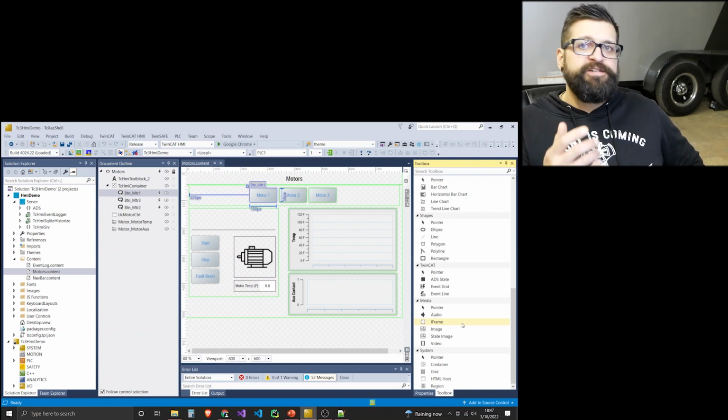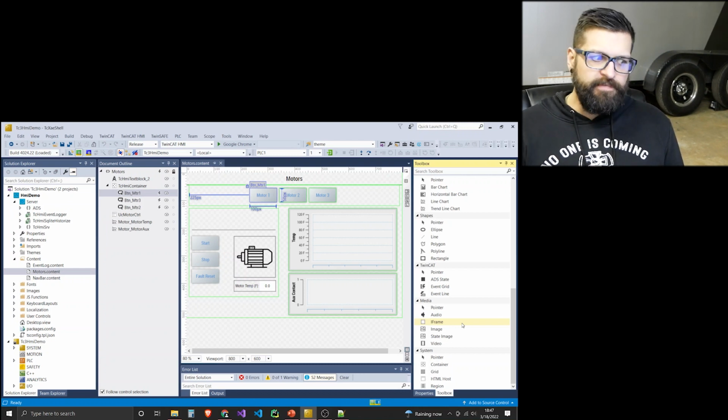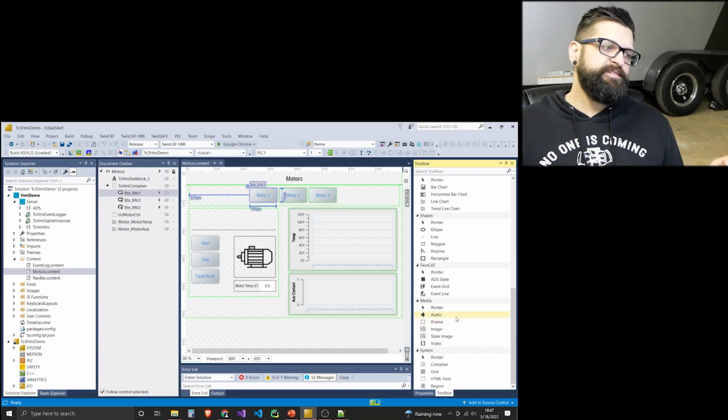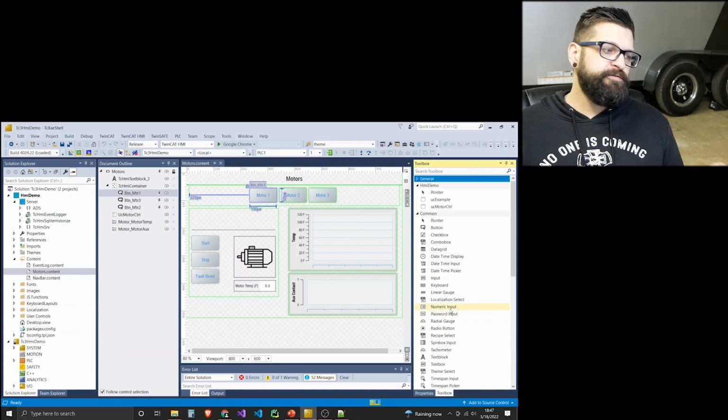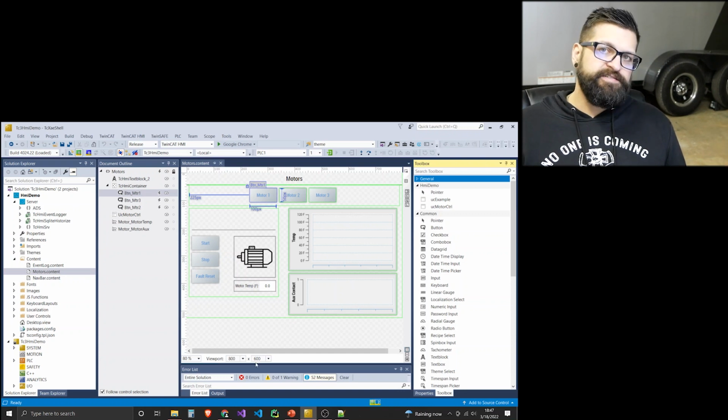So that's what we've done recently with a robot project where, in our TwinCAT HMI, we wanted to give the user the ability to look at the web server on the Fanuc robot. We used an iframe and we targeted that URL endpoint. So really nice features, and just getting yourself familiar with them is what's going to unlock the ability to create really awesome web pages. I should have done this earlier, but I will show you now everything that I've been discussing and talking about.